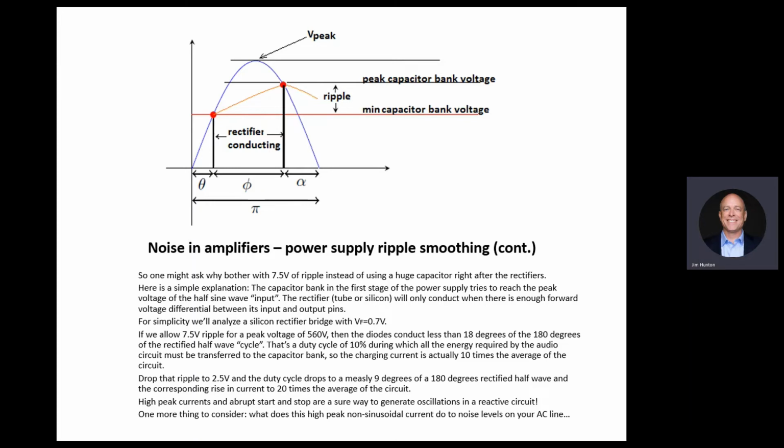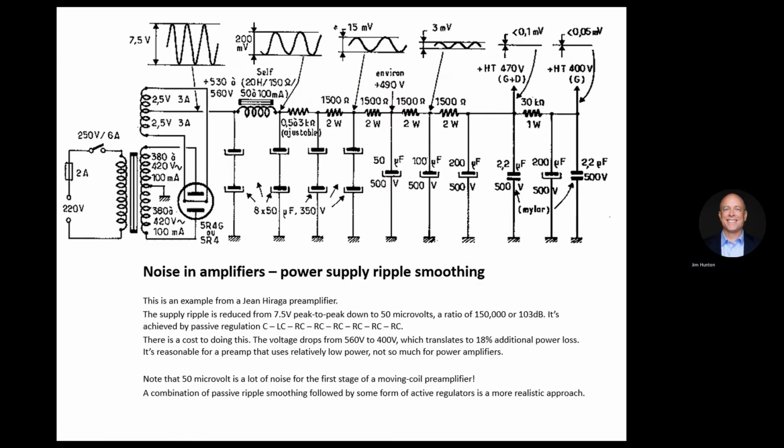High current peaks into circuits that contain magnetics are bad. Don't do that. Or capacitors. You basically have noise generators. Anytime you switch the diode switch on and off, you get ringing. You get a lot of noise in that region.